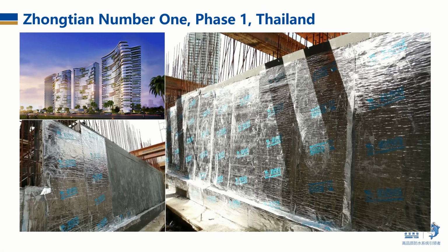As the substrate is in poor condition and the working space in some places is less than 1 meter, and the most important is the outside basement floor is poorly drained, so the torch-on method can't be done. It showed the wide adaptability of wet application.